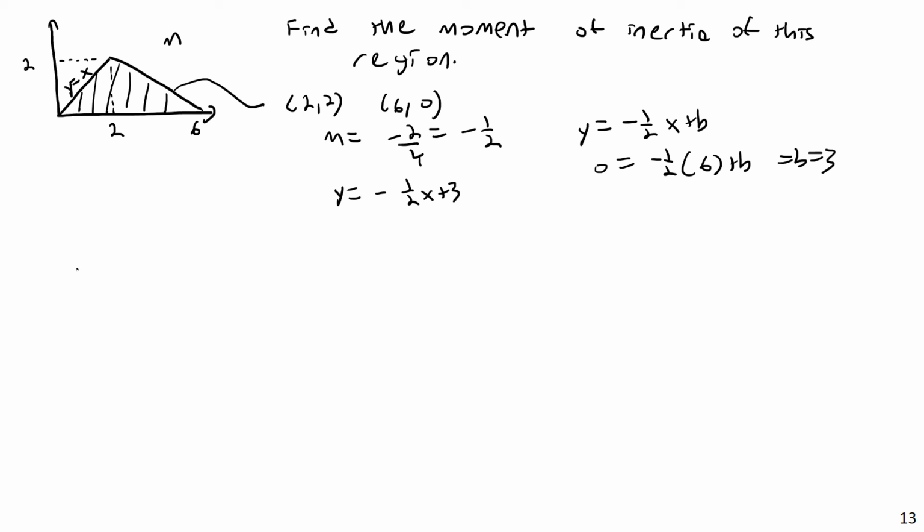So here, first of all, let's get the Iy, the moment of inertia with respect to the y-axis, and that's just going to be equal to the integral of y squared dA. Now, the tricky part is that we're using a vertical element of integration, and we can't use one equation to describe that dA across the entire thing. Instead, what I'm going to do is one integral from 0 to 2 of y squared dA, plus another zone of integration from 2 to 6 of y squared dA.